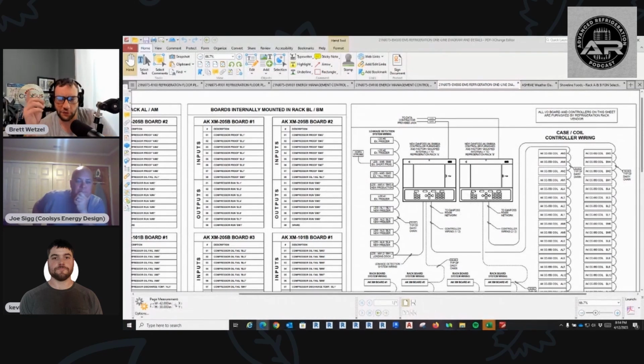So you'll rely on the customer to tell you how much heat they want to take away from this rack? No, we as the engineer figure out how much heat we can get out of the CO2 system. Then we tell the evap coil manufacturer or the heat reclaim coil manufacturer how much heat we have to offer, and they give us a coil selection based upon that heat.